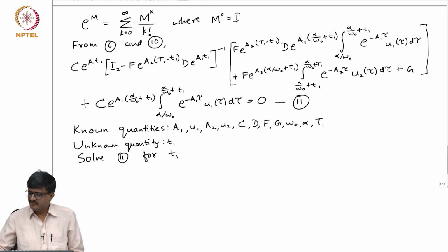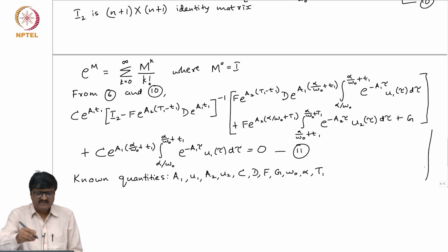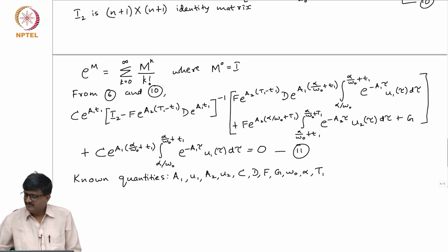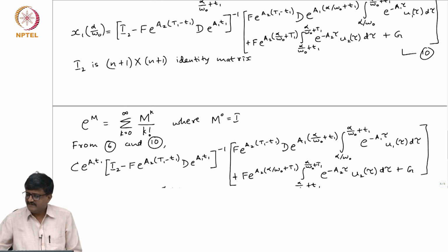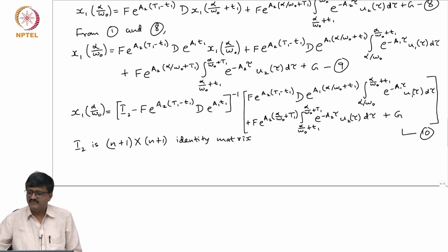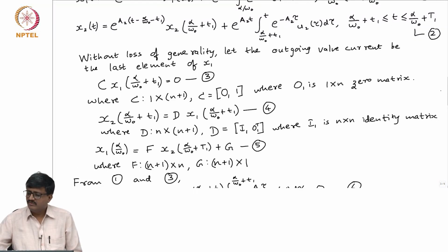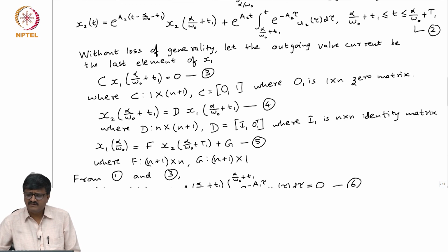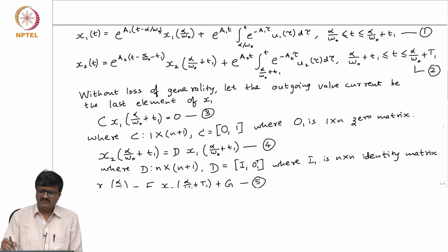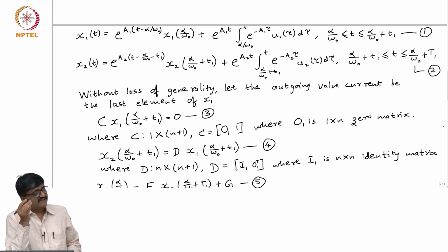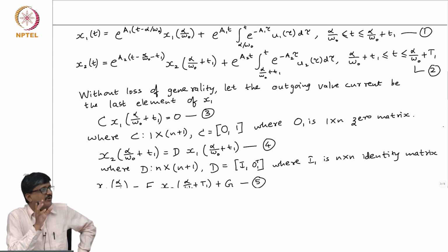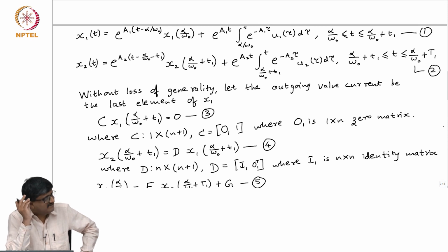See, go to the solution. What is the solution? Equations 1 and 2. Sorry, equations 1 and 2 are solutions, but they are solutions provided everything on the right hand side is known. M is nowhere coming in the equation. We will look at the size of M for different cases. M is right now not known. It depends on whether it is 2 and 3 valve conduction mode, or 3 and 4 valve conduction. That is not known now.